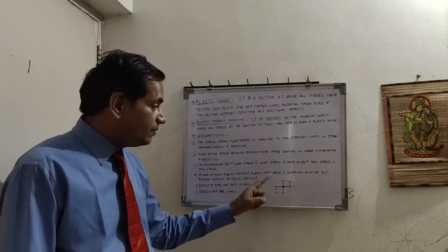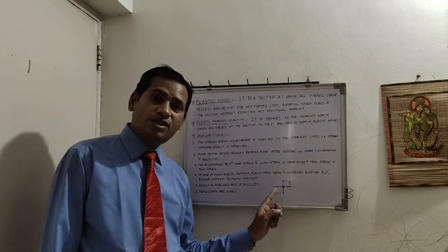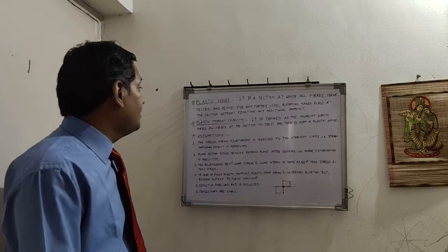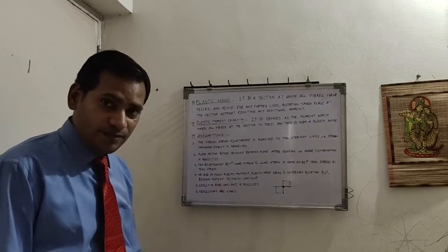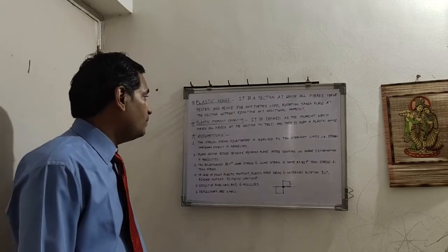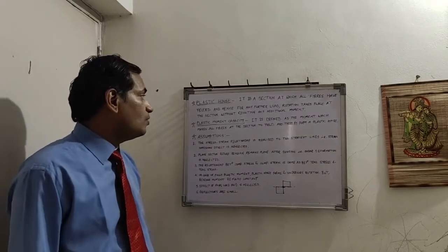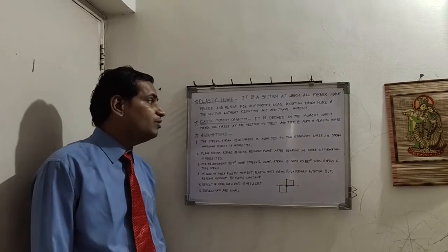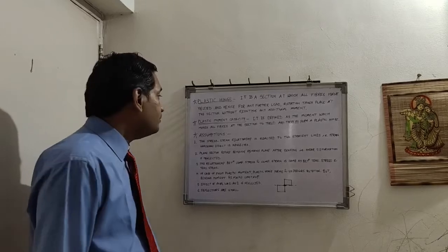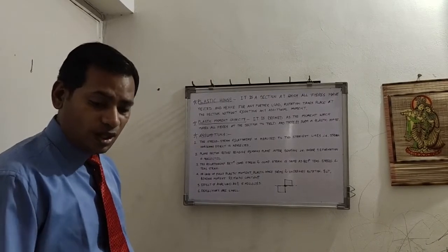After this stage has arrived for any cross section, there is no additional movement it can resist. Next is plastic moment capacity. Plastic moment capacity is defined as the moment which makes all the fibers at the section yield and thereby form a plastic hinge. Based on the previous session, these are two outcomes.